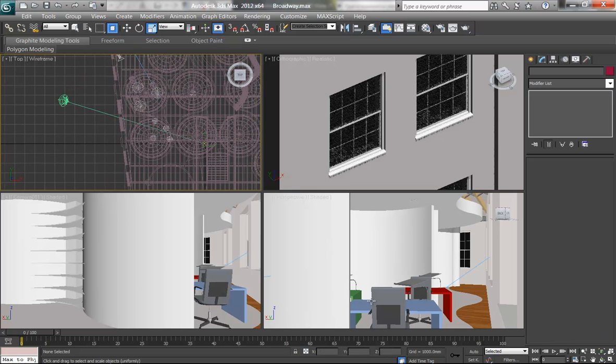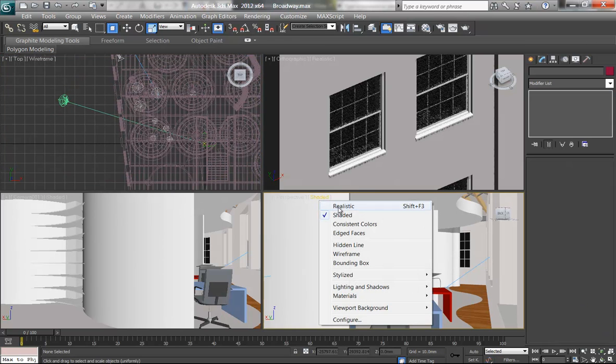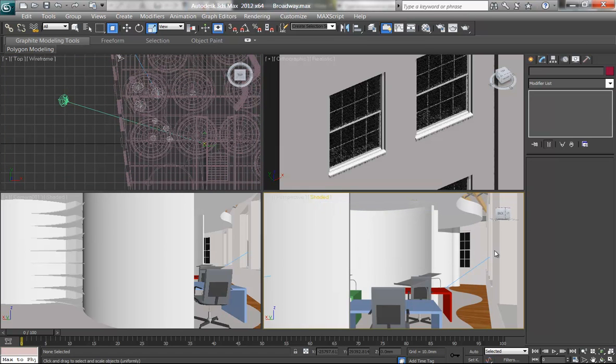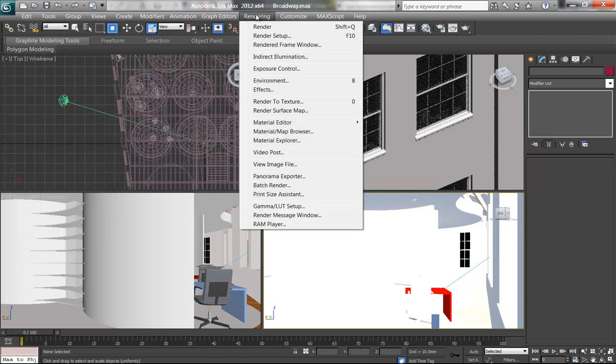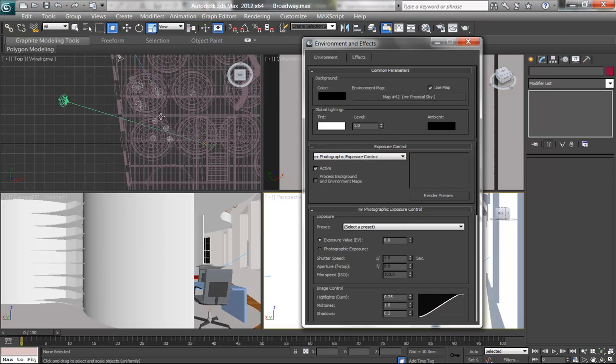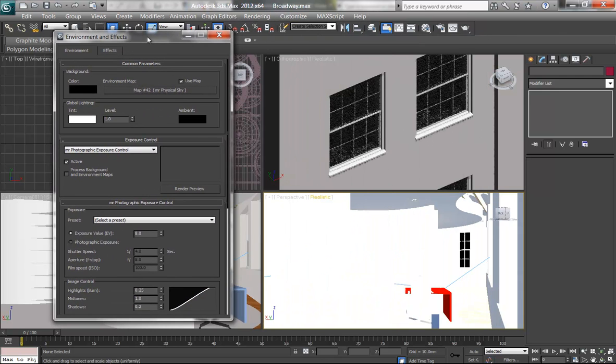And so now I can finally show you in the viewport, if I turn that to realistic, I should get light coming in through the windows. And that's a very useful thing. Now, it's coming in, but notice it's very, very bright. What do you think might be the final thing now? Think about if it's too bright overall. Exactly. So with interiors, you need the exposure under control because you have, in general, lower light levels. Your eyes are used to lower light levels because you're indoors.